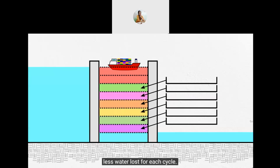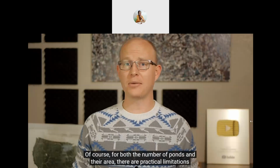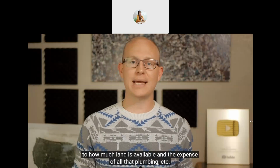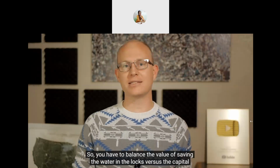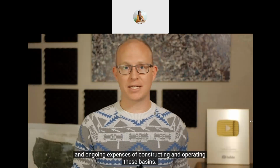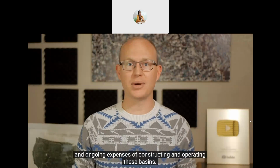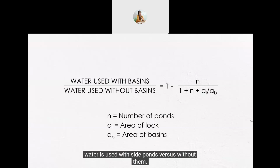Of course, for both the number of ponds and their area, there are practical limitations like how much land is available and the expense of all that plumbing. So you have to balance the value of saving the water in the locks versus the capital and ongoing expenses of constructing and operating these basins. That's made a lot easier with a pretty simple formula to calculate the ratio of how much water is used with side ponds versus without them.